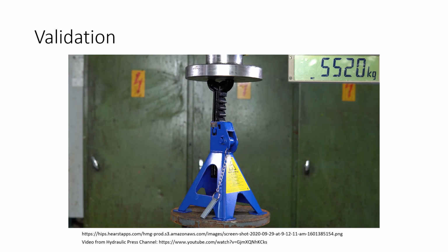Due to the complex nature of this geometry and important safety concerns of the product's application, the best way to validate the FEA results would be to do real-world testing. Some general hand calculations could be applied to give a ballpark idea if the model is accurate. Ultimately, the product should be manufactured and tested thoroughly in a variety of real-world conditions before it is tasked with the protection of human life. As you can see in the photo, one way of testing a jackstand would be testing how much force can be applied with a hydraulic press before the jackstand deforms or yields.